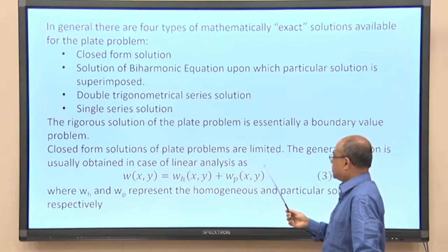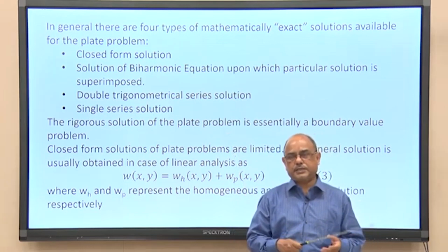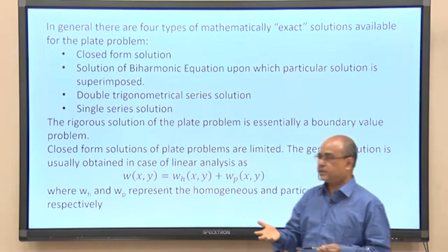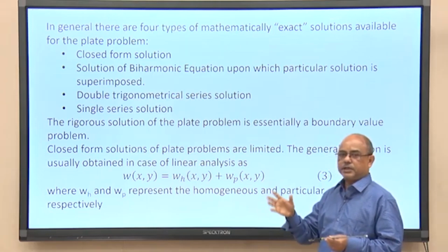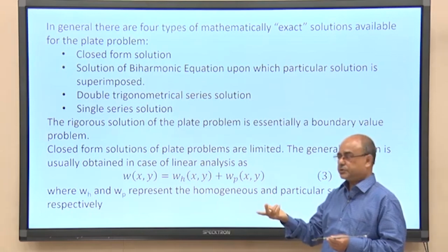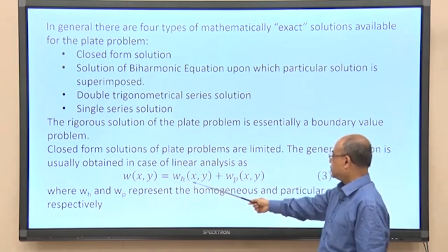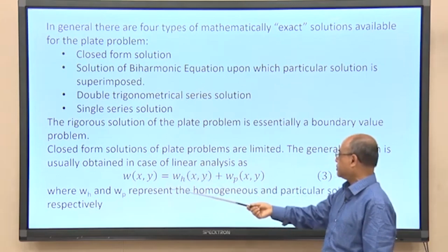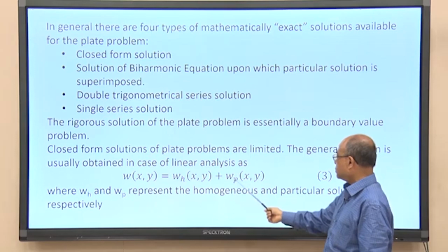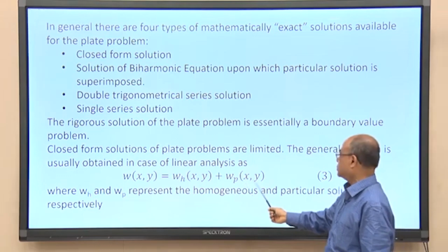Okay. So, closed form solutions of the plate problems are limited, that statement I am making here, and it is true. In many cases you will not get one, then you have to adopt numerical techniques, either finite difference or finite element techniques or any other numerical techniques, solving the differential equation, integrating the equations. Here W_H is the homogeneous solution of the plate equation, that means a biharmonic equation, and W_P is the solution for the forcing function that I call the particular integral or particular solution.